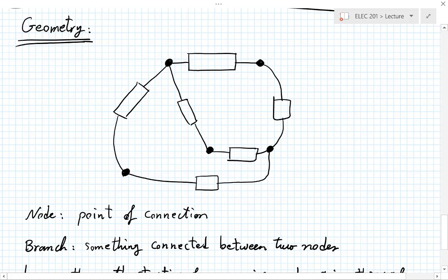Because really what matters, and you will see this when we write the equations, is the voltages and currents in the circuit. And these two branches have the same current. There is, in fact, a Kirchhoff current law that you can write here. But very often, as you get used to things and do them more efficiently, you might just realize from the get-go that these two have the same current and have this Kirchhoff law implied rather than explicitly write it.